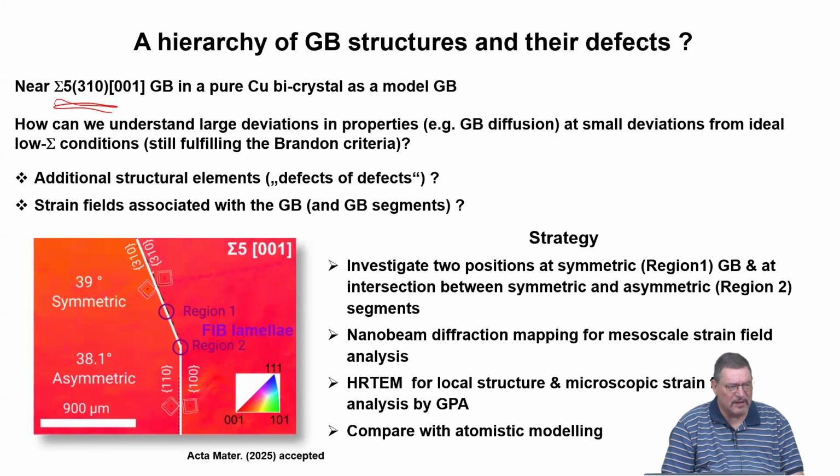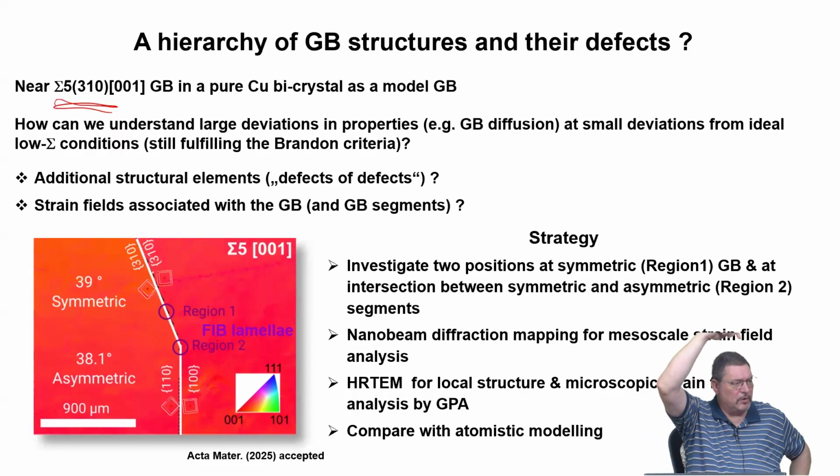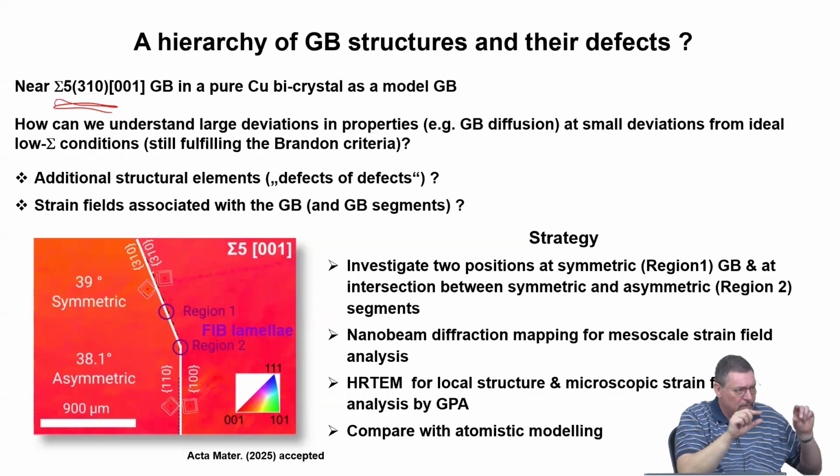And this is the EBSD image, so electron backscatter diffraction. You also know what it is? Okay, it's a scanning electron microscopy based method where you basically look at the signal of electrons which have been emitted by your electron gun, by your cathode, and which have been backscattered from a very thin region of your crystal into a detector which is situated at a certain angle.